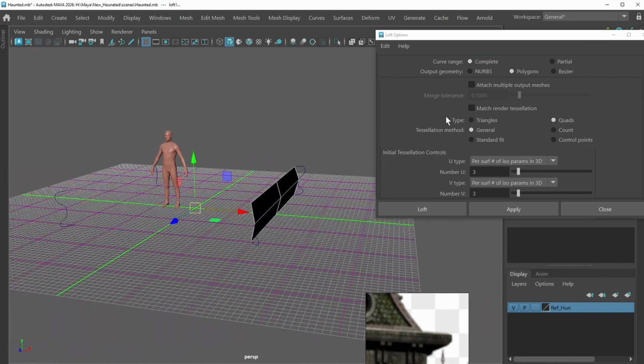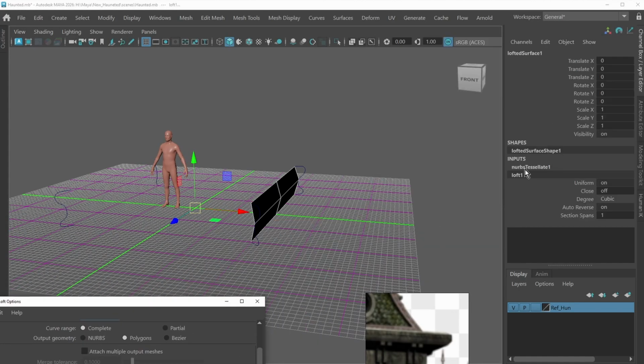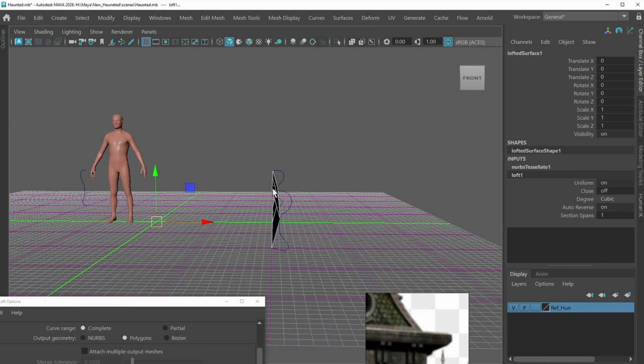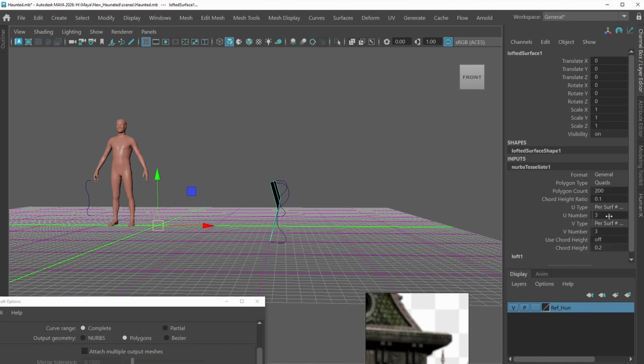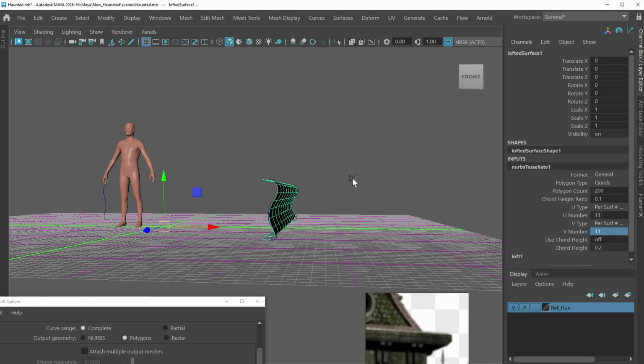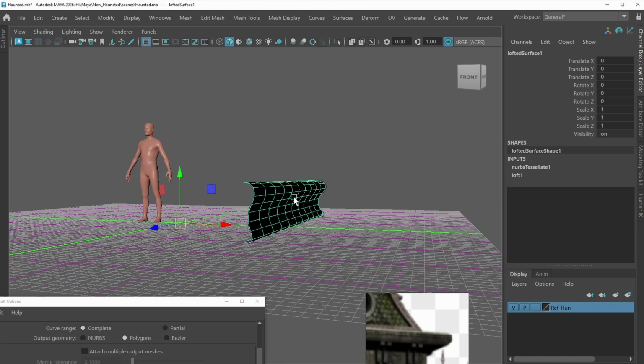It becomes reversed here. So I'm going to move this to the side here now to fix this shape to make more of the shape of the profile. Click this here, NURBS tessellation, and type 11 and then 11 here. And now when I hit 3, you can see it takes the shape of that profile.